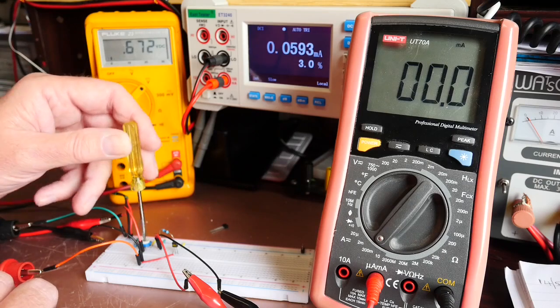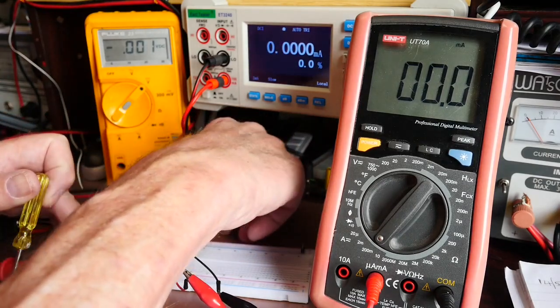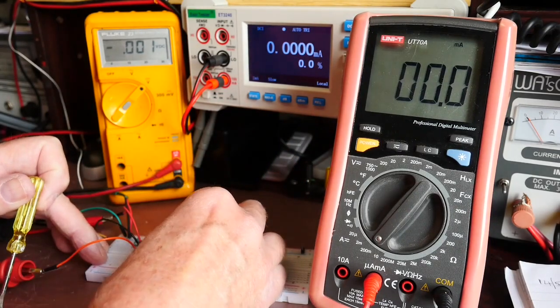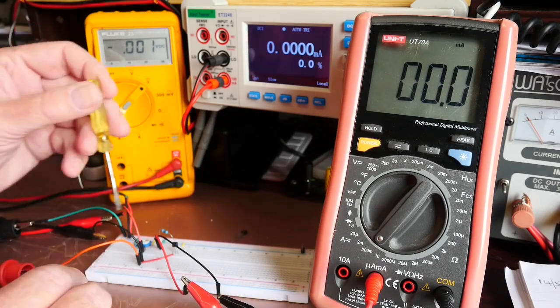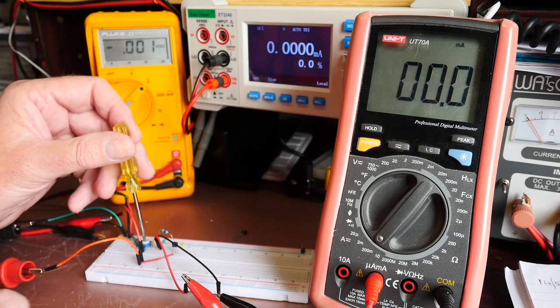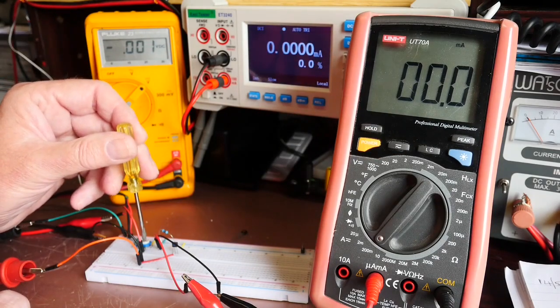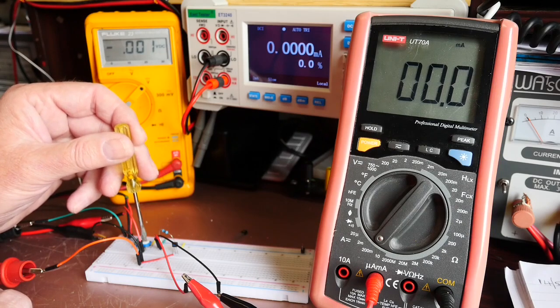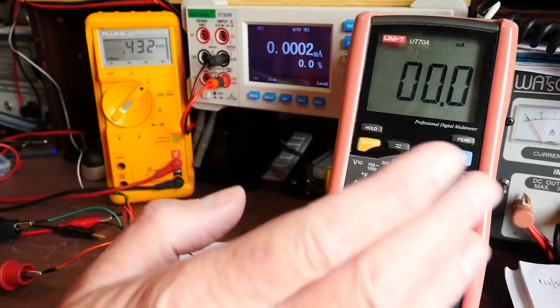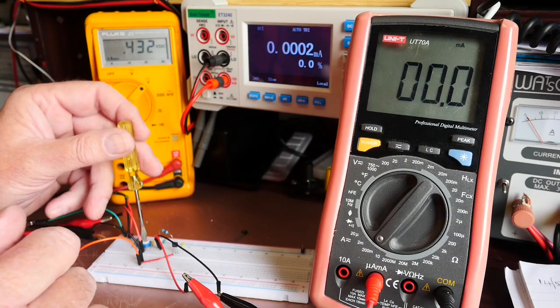And I'm just going to switch that all off, and we'll swap onto the blue transistor just to convince you that its characteristics are going to be similar. So that's the blue transistor in position. So no current, no volts, so I'm going to increase it as best I can without getting too keen on this control. I'm going to go up to about 0.45 volts. So there's 0.45 volts, just beginning to get a hint of base current, but still no measurable collector current.